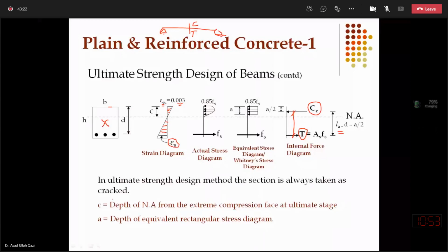So knowing these strain magnitudes at the cross section, which is the mid-span cross section, I can draw the stress diagram. For the material concrete, I know that when 0.003 comes, it means the concrete has approached 85% of its peak.